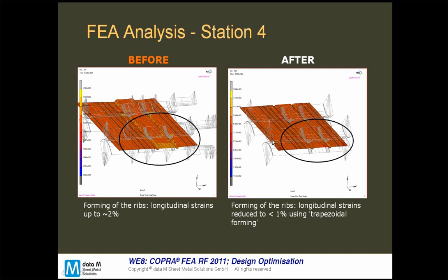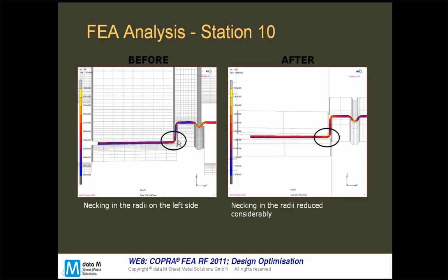flow of material, and again in this movement a little bit slowly at the end. This trapezoidal bend strategy makes the material flow much better and softer, and we can see that there is no longitudinal elongation anymore. This difficulty for the material to get to the inside also is visible in the simulation because of